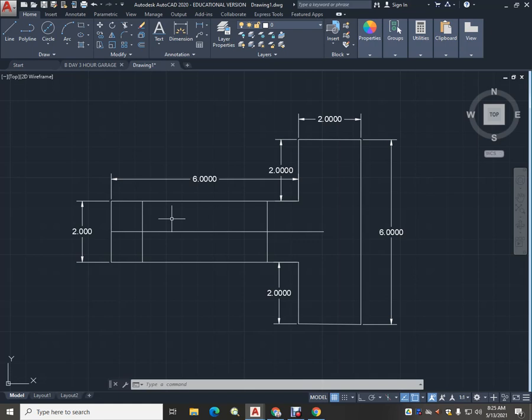It works a little different though, in that once you engage the offset command, you must put the offset distance in first before you touch any part. So it needs to work that way. Distance first, and then you can touch whichever thing, part, line, circle that you want to offset, and then put it in there.